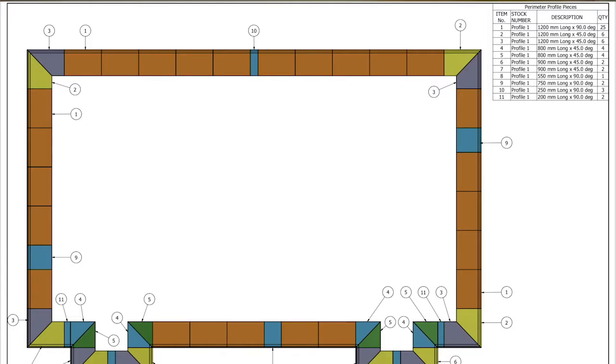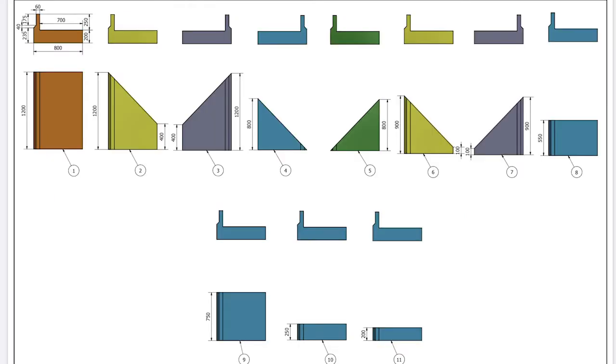When the Core technical team creates the installation drawing, this is basically a key plan that goes to site. Each piece of the foundation system is numbered and indicated on this plan. We give sections, and obviously a plan overview of how the system works, where any internal load-bearing walls may be located, and sections through showing the actual profiles themselves and how these go together.